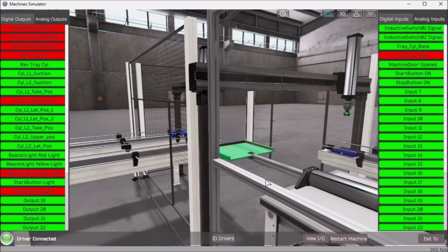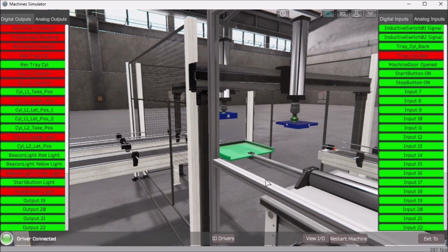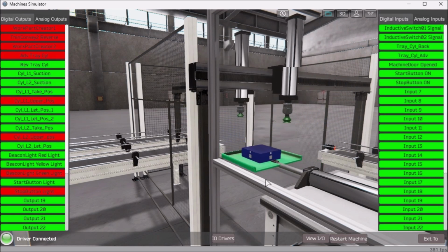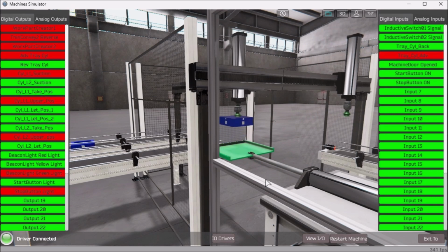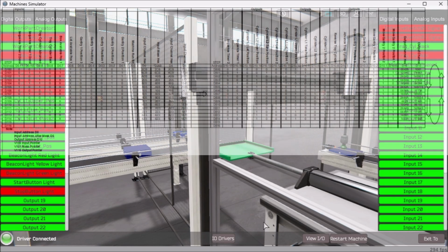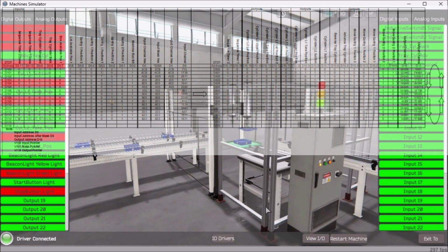If your program works correctly, it's time to move on. If not, you'll need to debug. Since we are using indirect addressing, troubleshooting and modifying can easily be accomplished. This can be as simple as downloading and uploading your program, or as complicated as redesigning your logic altogether. Amendments to the sequence table and the corresponding PLC sequence tables will quickly change how your logic works.